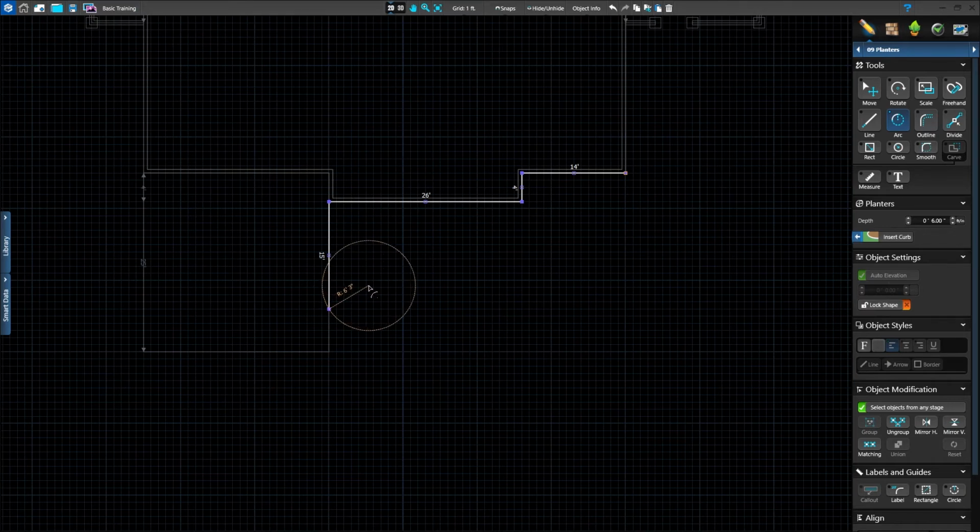We're going to make a total of 5 arc segments, so we'll estimate how long each arc should be. Draw the first segment and left-click. Our next segment will go in the other direction. We'll move our mouse down this time to create an arc going the other way. Click to set it and trace the portion we want. We'll repeat this process 2 more times.